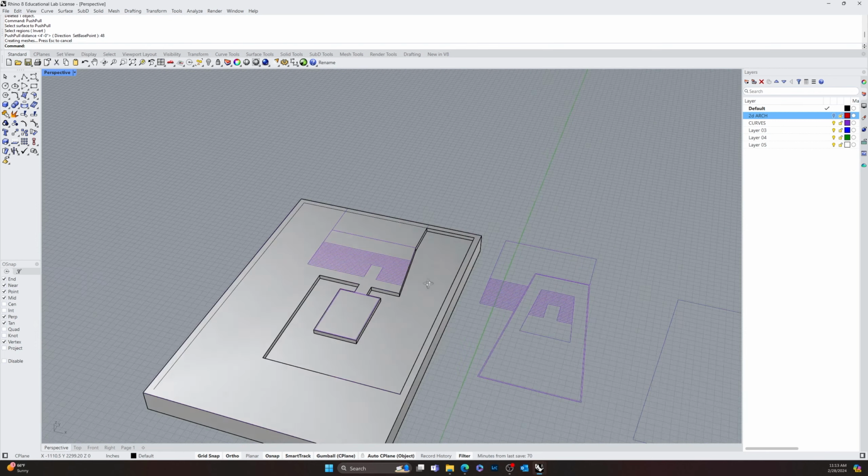Next, we're going to take our pool and let's create some water with it. So Control Shift, or Command Shift if you have a Mac, click, and then I'm going to extrude this up, and I want like a 2-inch lip where the water is. So I'm going to go 46 inches up, extrude 46. And we don't use push pull for this because we want it to create a separate secondary object. Ooh, it didn't though. So then I'll go extrude surface, enter. And then click on the surface, enter. And I'm going to go 44 inches. Yeah, and that makes a separate one. Okay.